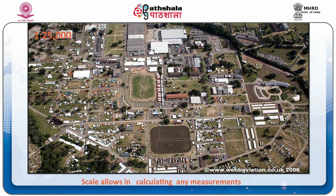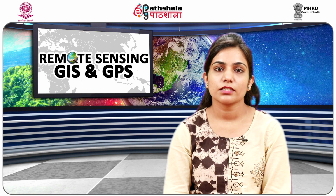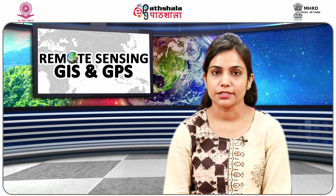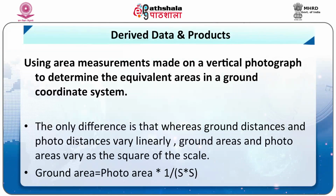For example, if a 1 kilometer stretch of highway covers 4 centimeters on a photo, the scale would be 1:25,000. The next information we can derive is determination of equivalent area in a ground coordinate system using area measurements made on a vertical photograph. The only difference is that whereas ground distance and photo distance vary linearly, ground area and photo area vary as the square of the scale.